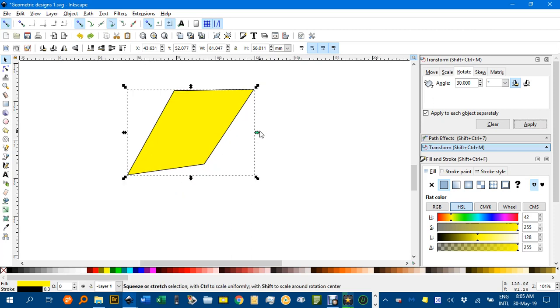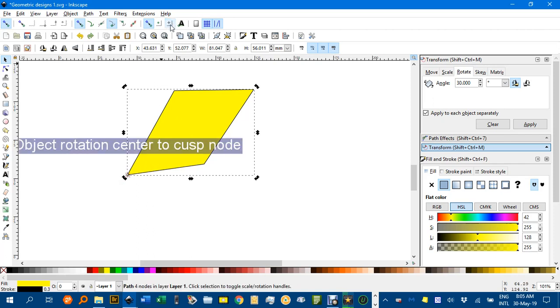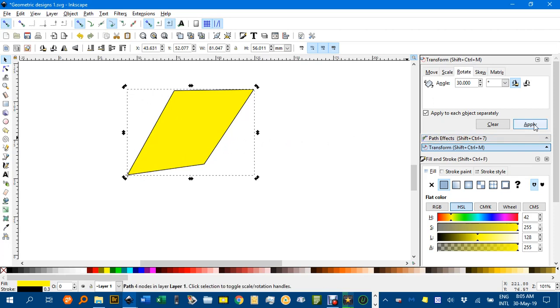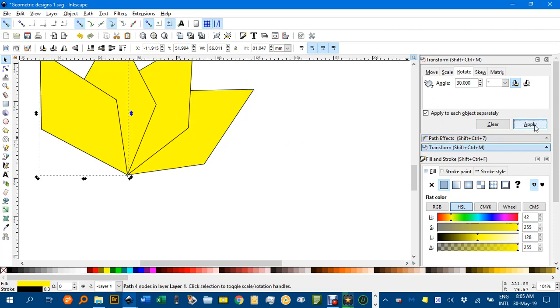So I Control-Z a couple of times, I go back to my original shape, click a second time, there's the centre of rotation. I'll drag it till it snaps on this corner. You must have this icon, the snap to rotation centres, on. Now that my rotation centre's there, I can rotate about that point. So back to Control-D and apply, Control-D apply, and I'll just keep doing that.